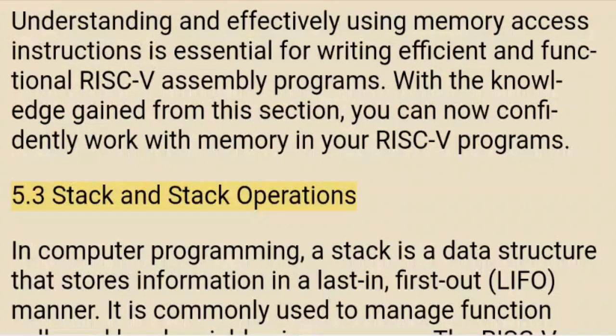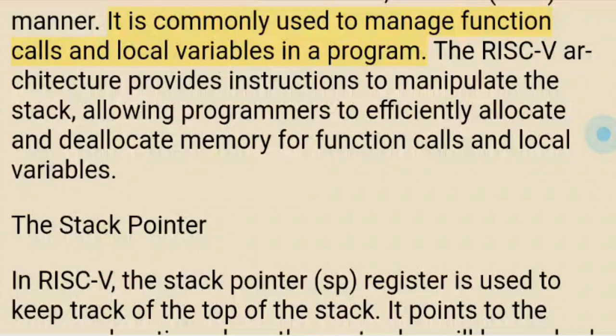5.3 Stack and stack operations. In computer programming, a stack is a data structure that stores information in a last-in, first-out (LIFO) manner. It is commonly used to manage function calls and local variables in a program. The RISC-V architecture provides instructions to manipulate the stack, allowing programmers to efficiently allocate and deallocate memory for function calls and local variables.